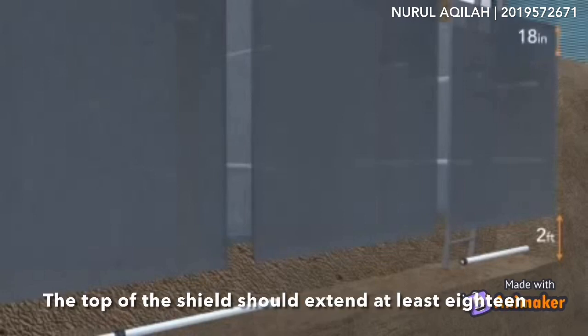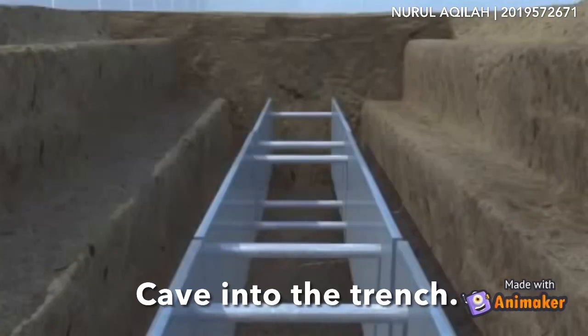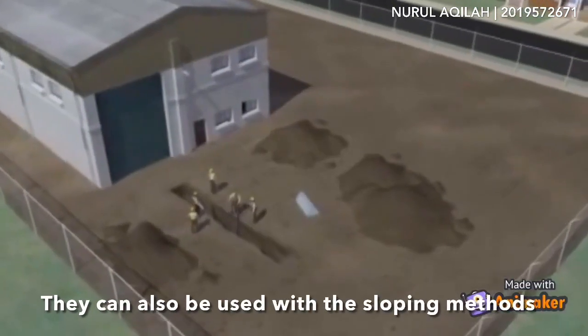The top of the shield should extend at least 18 inches above the level of any material that could cave in into the trench. Trench boxes are typically used in open areas, but they can also be used with the sloping method.